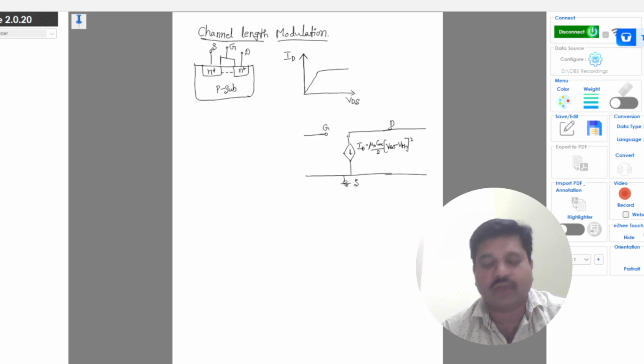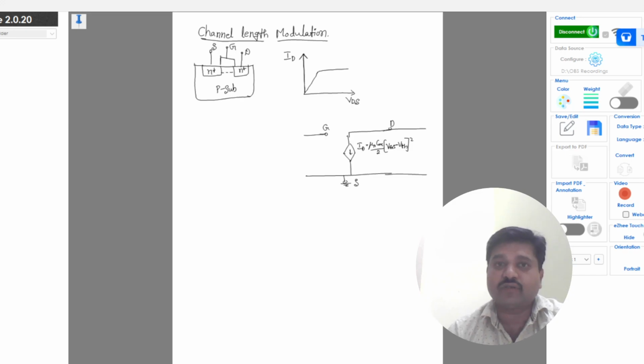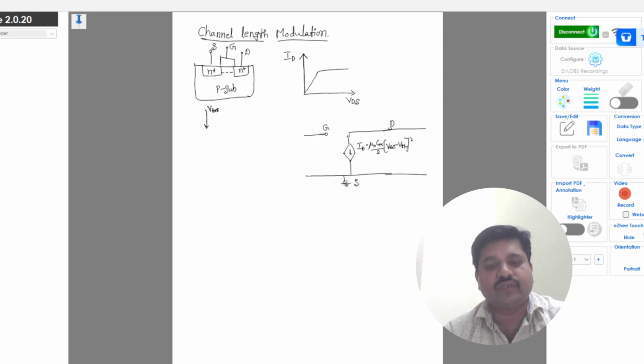of operation. Basically, we discussed two different fields. One is the vertical field, that is due to the voltage VGS. Corresponding to this, we discussed the different regions of operation for the MOSFET: accumulation, depletion and inversion. And we start applying the horizontal field, which is VDS. The horizontal field is due to VDS.